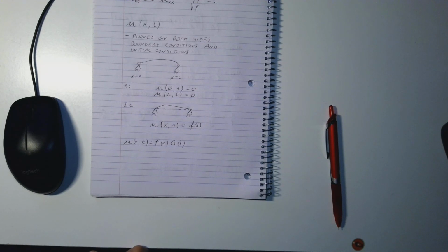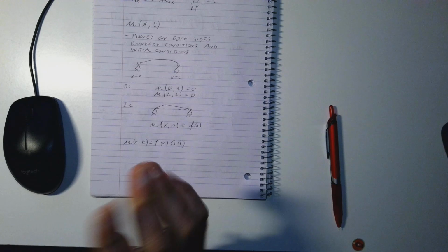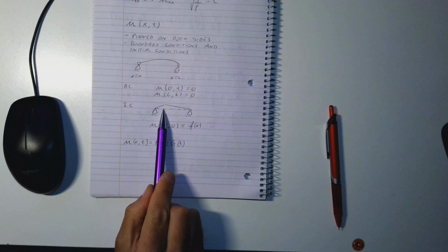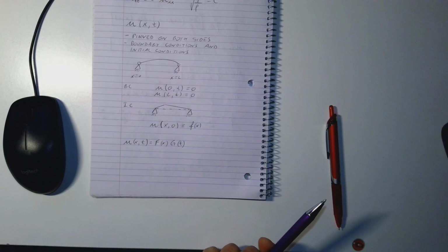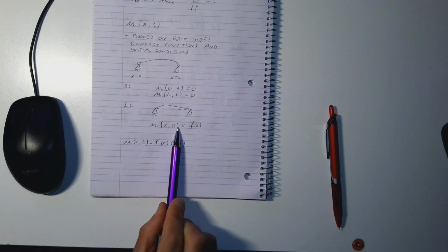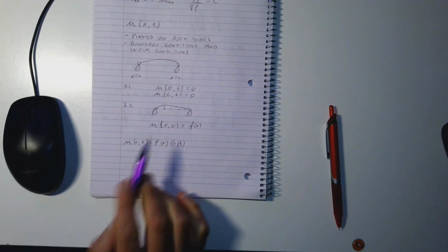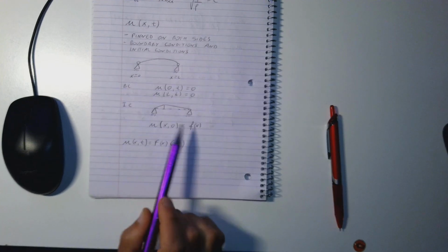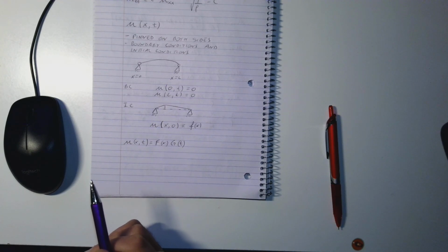So at the beginning of your timeline, you can say, okay, for a certain point, I give a certain displacement. You can even give a certain velocity. But of course, since it is a continuous system, when you apply a displacement for one point, all the other points will be influenced as well. So that's why in this case, when you look at the initial condition, when you give a displacement of one point, all the other points will be influenced as well. So you will need to determine a function for this initial condition. Makes sense?